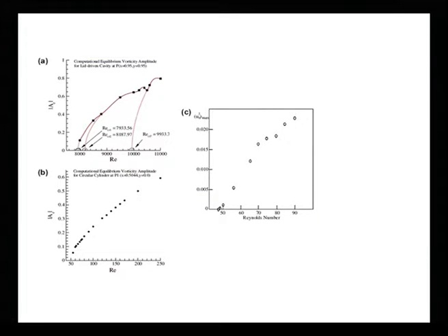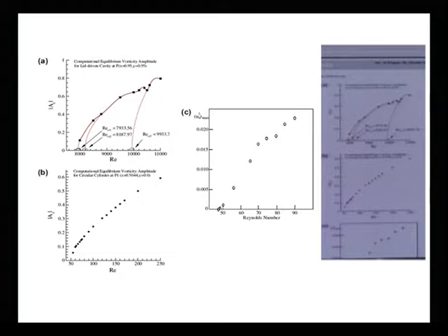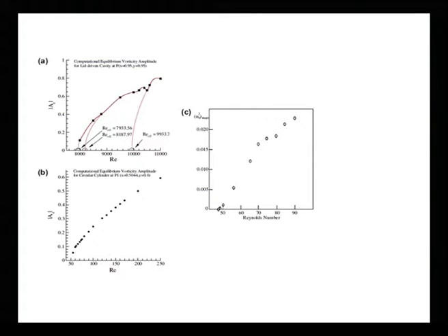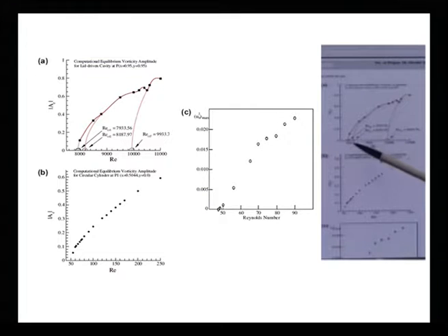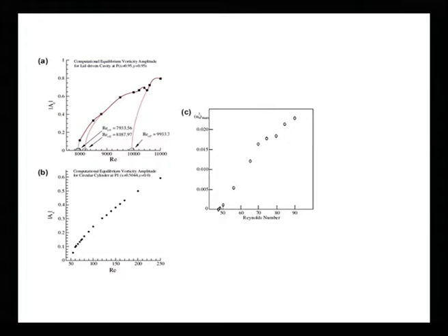As you can see, the first one is around 7,933, the second one is at 8187, and the third one that we have shown here is 9933. So, essentially whatever we have seen for flow past a cylinder is depicted here, and the corresponding experimental results by Strykowski are shown here. You do get to see exactly a similar phenomenon: it is not purely given by the Landau equation, it falls on various branches of bifurcation, and this of course lends credibility to what we have been talking about in terms of the universality of this kind of instability modes.